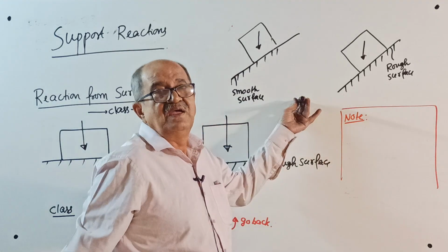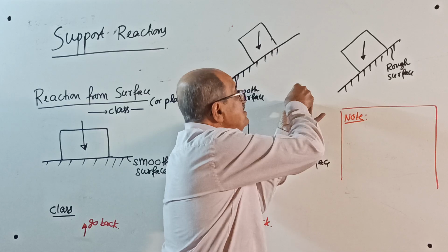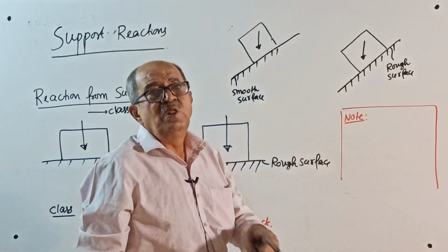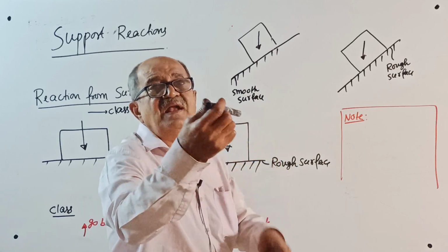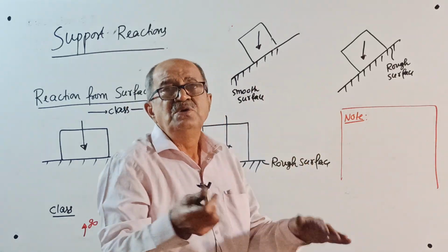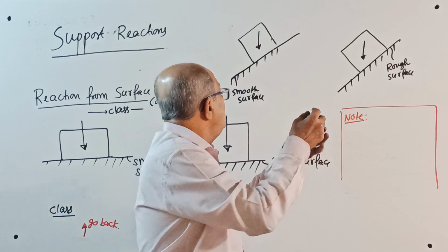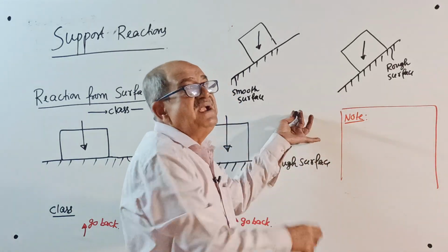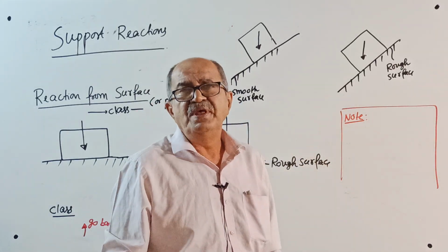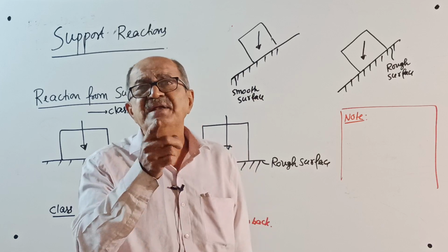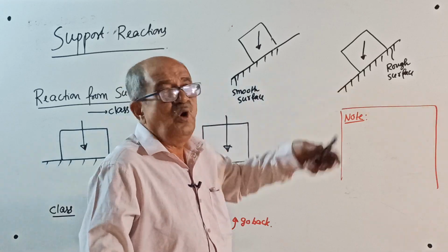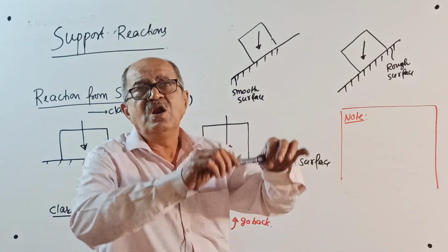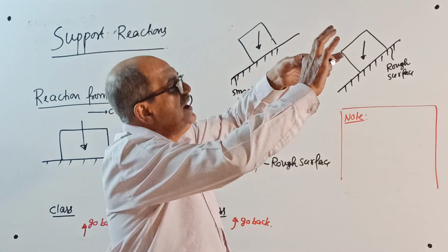Finally, I will come and touch the board. See here now. If the force is applied, this board will not allow the pen to move further. Earlier, displacement was allowed, so no reaction. Now, displacement is prevented. Yes, when displacement is prevented, there is a reaction from the support on you. Or, suppose I hold a pen here this way.